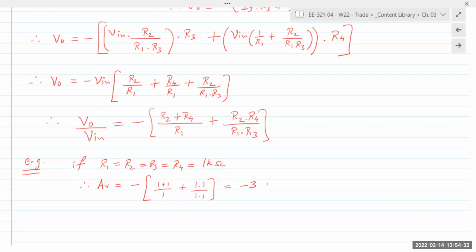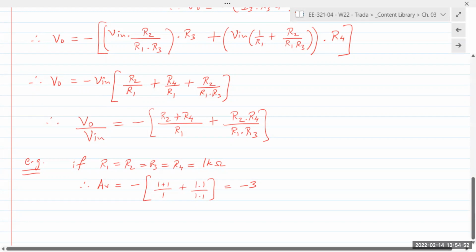Now, let's say you had 10 quantities of resistors with only one value each. Let's say 1 kilo ohm and 10 kilo ohms. Gain with a standard configuration would be 10 over 1, a gain of 10. However, if you built the circuit with those same resistors, and let's say we put in R1 equal R3 equal 1 kilo ohm, and R2 equal R4 equals 10 kilo ohms.